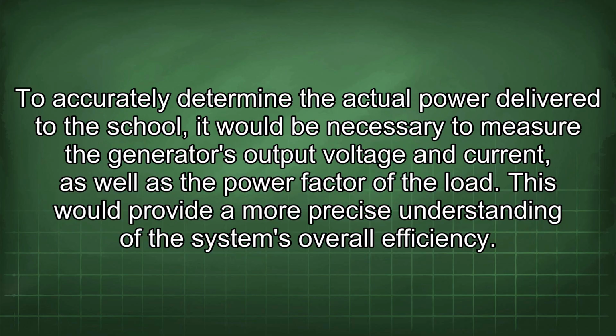To accurately determine the actual power delivered to the school, it would be necessary to measure the generator's output voltage and current, as well as the power factor of the load. This would provide a more precise understanding of the system's overall efficiency.